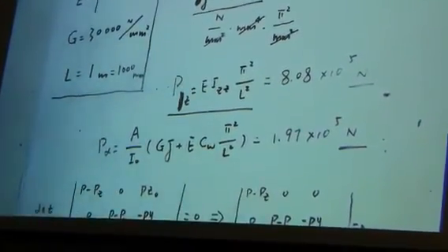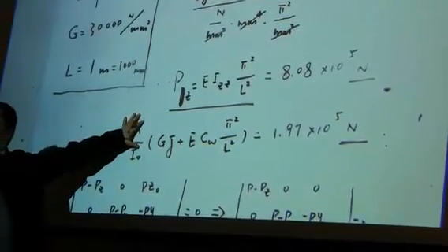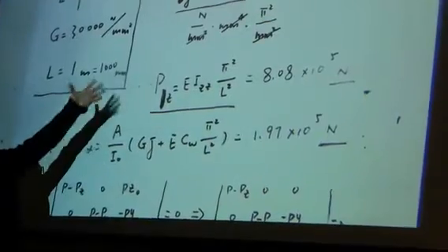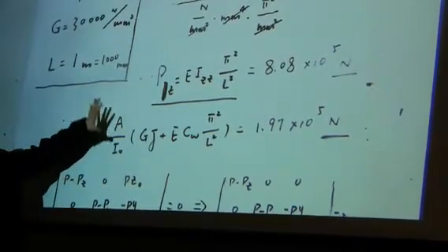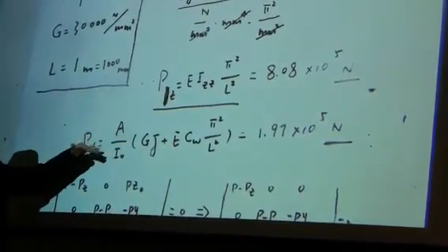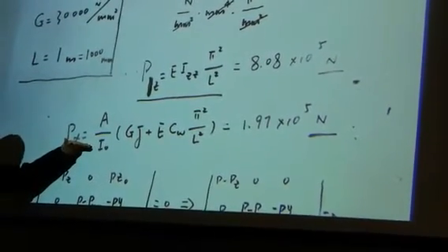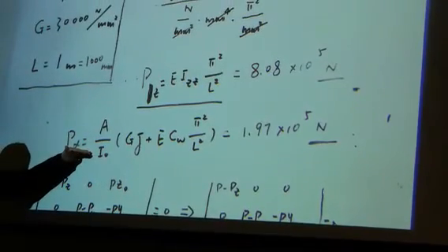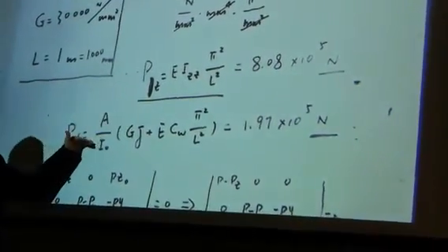So if your calculated loading is larger than one of these three values, maybe the minimum loading should be one of these three. See what I mean? If your calculated P is larger than one of them, Py, Pz, and P alpha, that means your loading cannot achieve that P you calculated. The buckling will already happen due to Py, Pz, or P alpha.